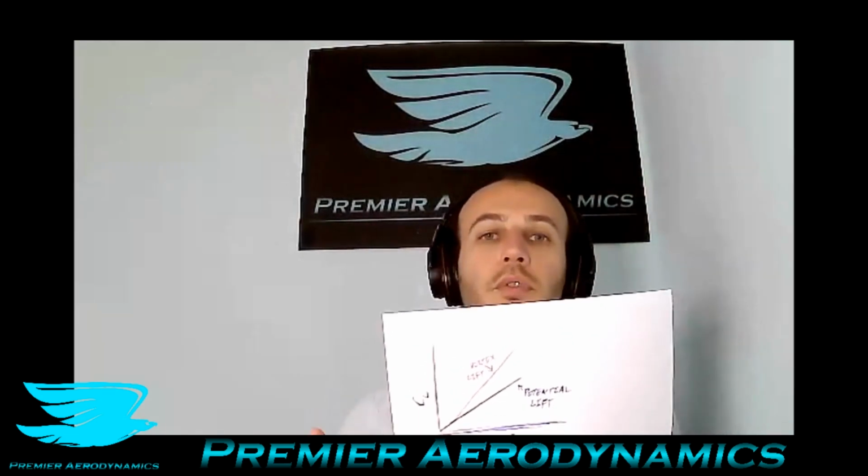Now we'll go into explaining why that is, but it's important to note that this vortex lift is able to produce more lift than just the regular potential lift. So together, they can produce even more lift than a regular airfoil. There are some caveats that I'll get to in a second, but that's why delta wings are suited to producing high lift, especially if the leading edges are not that swept. The reason is that in order to produce this vortex lift, you need to have a vortex, hence the name, and you get a stronger vortex with a not as swept leading edge.